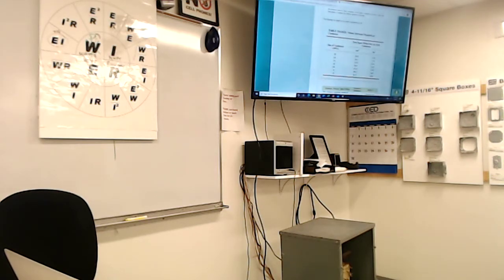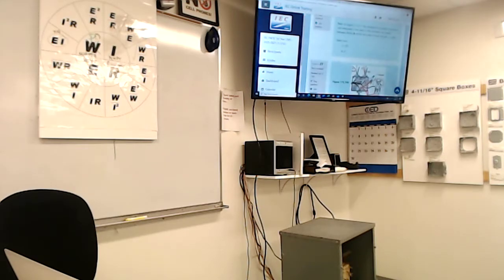Let's go back to the question. So they want to know if I put 2 metal switch boxes together, 2 switch boxes, we know now, after diligently researching, what size switch box is. Which one is the switch box section in table 314.16(A)? What's the switch box section? We just figured out what that 3 inches is.